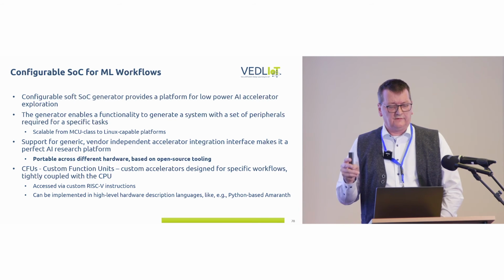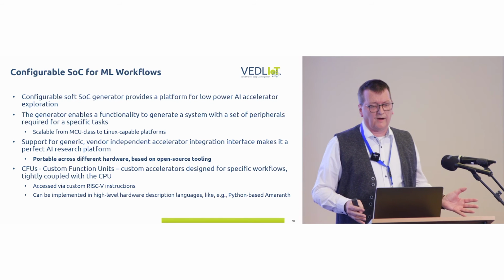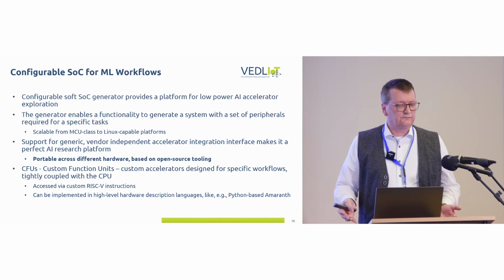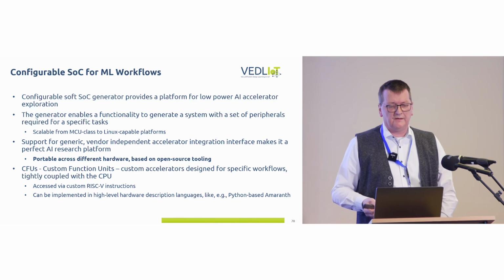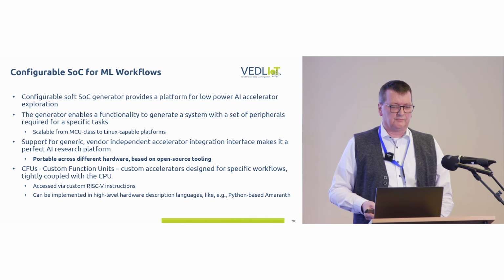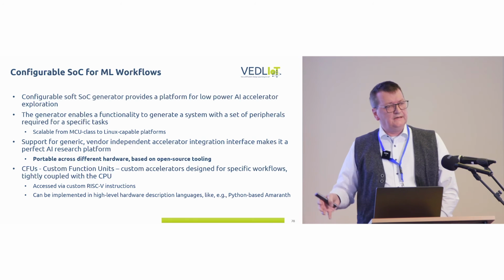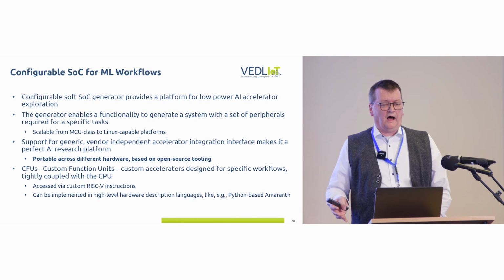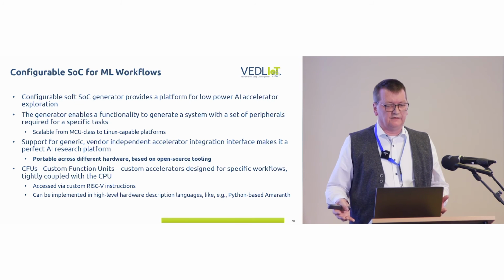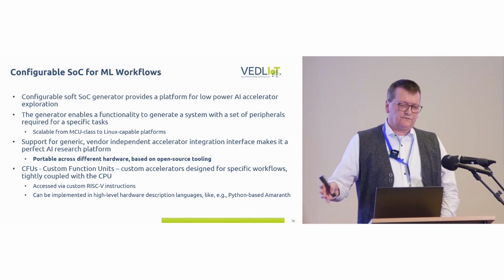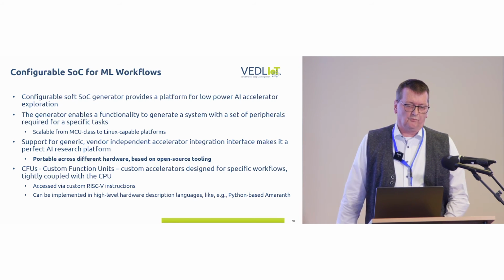So the idea is that the generator enables you to generate the complete system-on-chip environment with all the peripherals required, and you can go from simple microcontroller unit size RISC-V implementations up to Linux-capable platforms. The idea here is to have a vendor-independent accelerator integration, so that you can port your implementations of accelerators, for example, across lots of different hardware platforms, and everything should be done using open source tools.